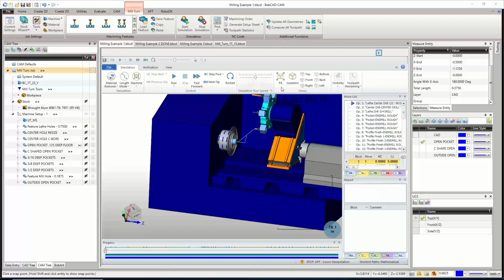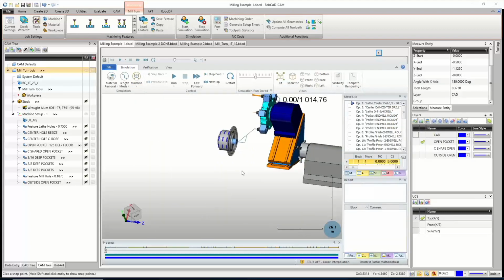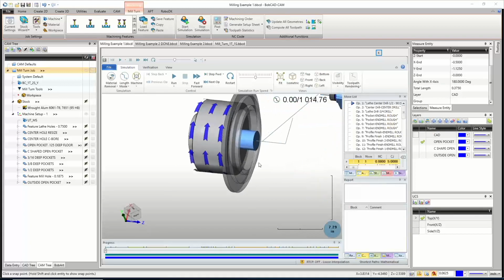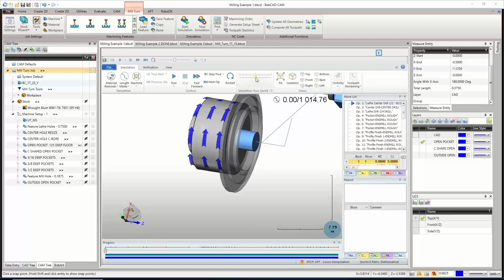If you do have a big chunk of machine kind of as the back, I really only care to see the spindles, the turret, and really that's it, and the tools. So if you go to toolpath rendering here, if you're on the machine mode and you can see the whole machine, go to visibility and then machine housing, and you can actually hide that whole thing, so it'll disappear. Mill turn's one of the most difficult ones to line a good view up with, I feel like. So I'm just going to keep it kind of slow right in the middle there.